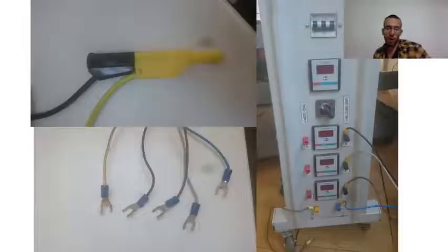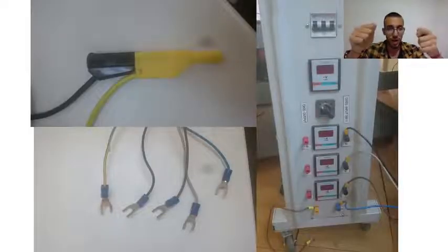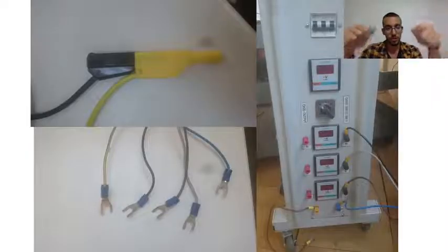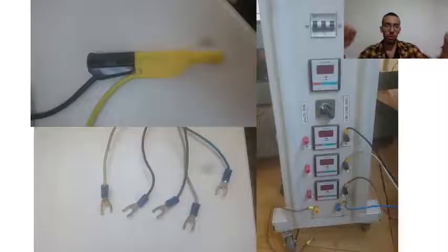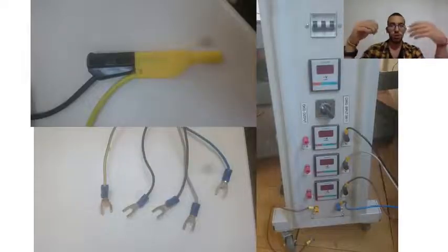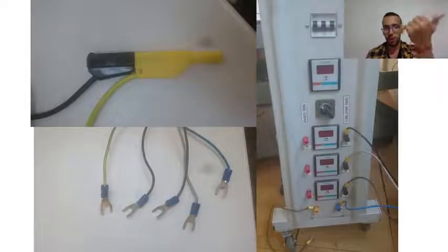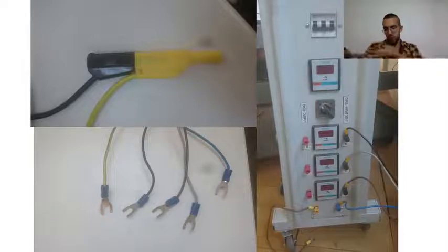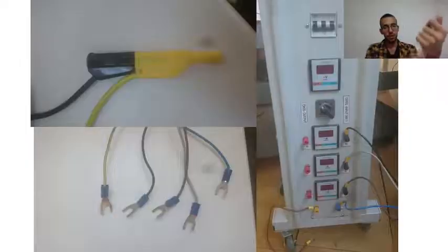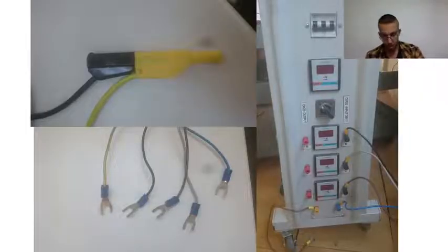So why the right hand? If possible, try not to work with two hands, because you may make a closed circuit with the equipment. You're touching the equipment, and it could be a closed circuit, and the current could flow from here. We don't want that, so one hand is better. But why the right hand? Because the heart is on the left, and we don't want the current to reach the heart. If we're using our right hand, it is more difficult for the current to reach our heart. That's the reason.